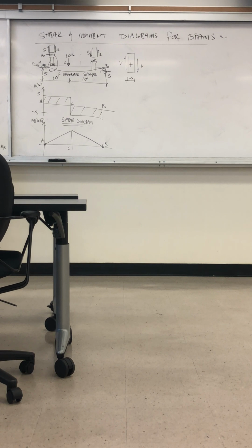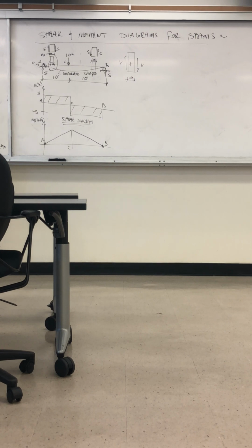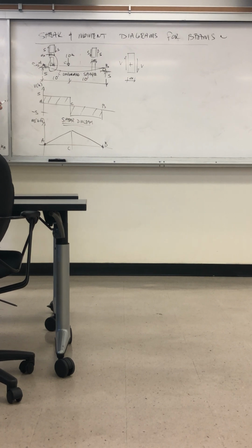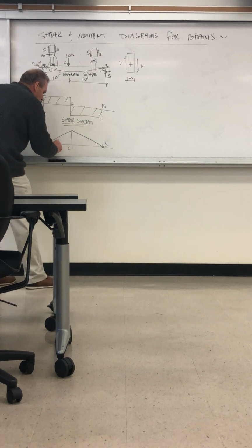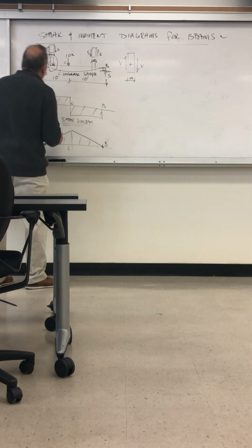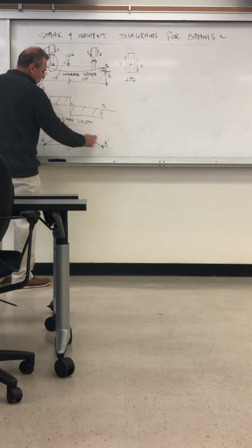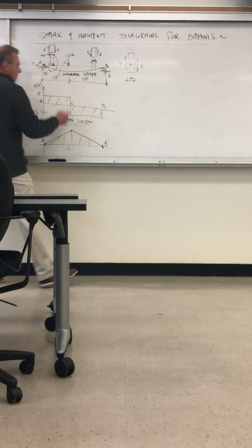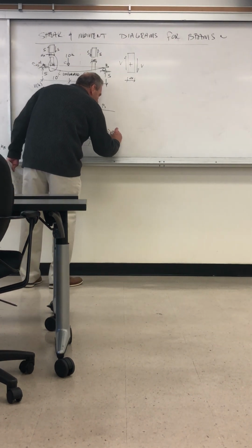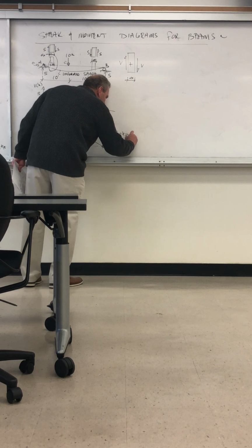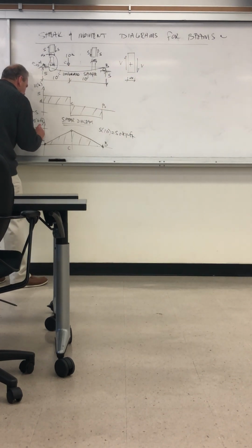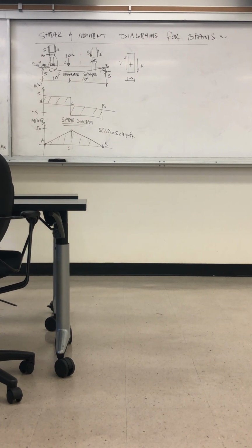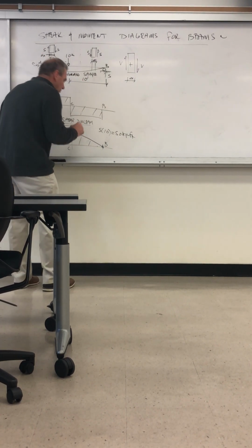And again, each cross section is not just resisting any shear force across that section with the shear distribution equation of VQ over IB, which we'll see later, but each cross section is also resisting its own moment. It has this shape like this. In this case, we only had to calculate 1 point, which is 5 times 10, equals 50 kilo-feet. This is 50. That's it. So that's the shear diagram. This is our moment diagram for this particular structure under that load.